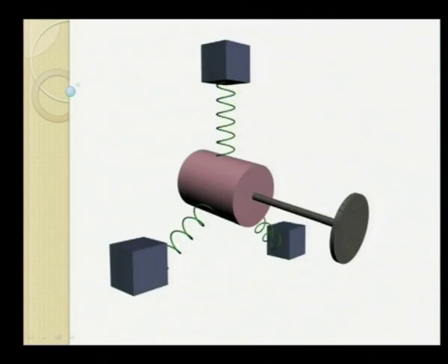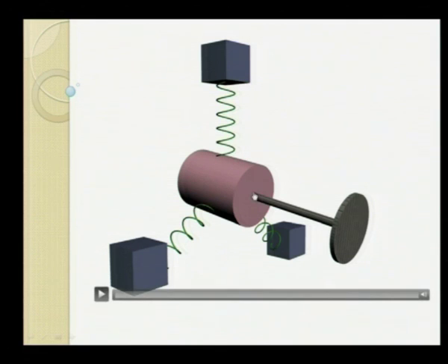This is the animation for the motor and the shaft whirling. This particular motor is whirling because it is mounted on some spring which is providing torsional stiffness, and the spinning is very fast. So here we will see the whirling and the spinning frequencies will be different.